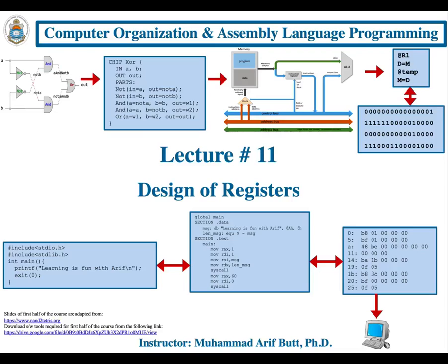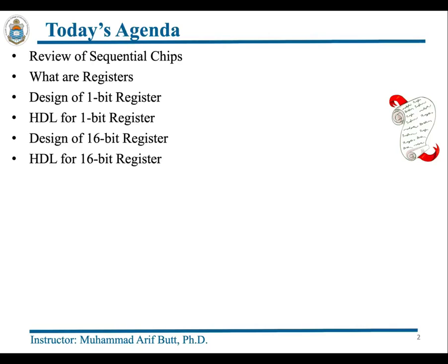The title of today's session is Design of Registers. Well, today we will start with a quick recap of the sequential circuits, which we talked about in the previous session. We'll talk about the concept of CPU registers. Then we will design and write HDL code for single bit as well as 16-bit register using the built-in D flip-flop chip. And finally, we will verify the behavior of our designed chips by loading and running them in the hardware simulator. So let's start playing.